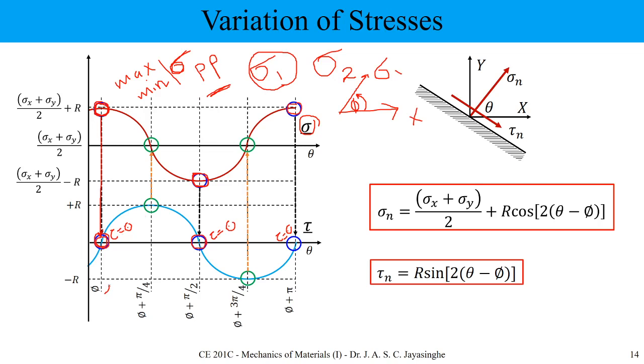You can see it clearly here. When we rotate this plane to φ plus 90, that means for 90, we can see the second principal stress, or minor principal stress. At those planes, τ equals 0: no tau, no shear stress. That's the most important thing.